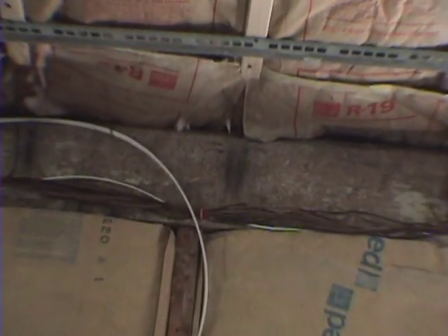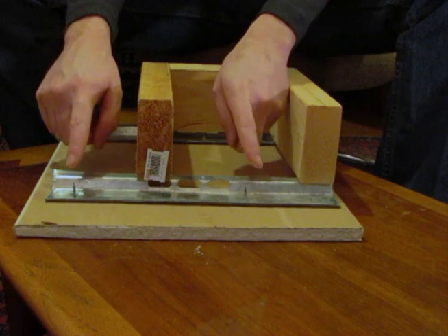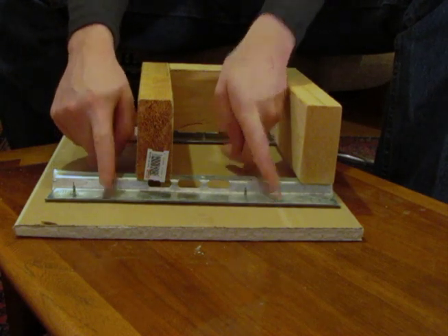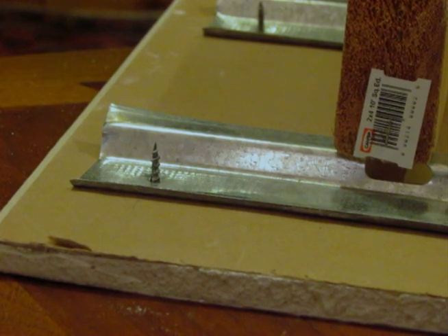Before you start hanging drywall, it pays to mark where your ceiling joists are and where the RC is so that you can put the screws in the right place. We took a can of black spray paint and made marks on one wall where the framework is and on another wall where the RC is. The idea is to put the screws so that they go through the drywall and the RC, but not into the frame. By marking the placement, you can be assured that the screw is in between the framing.